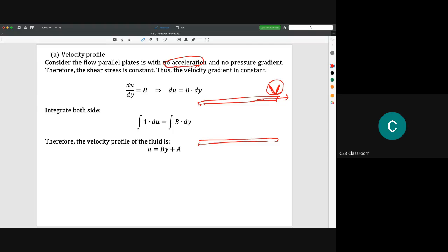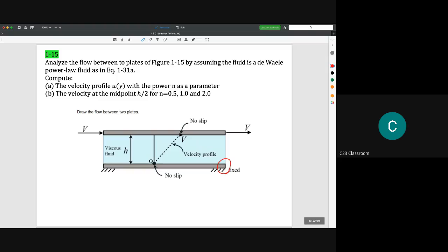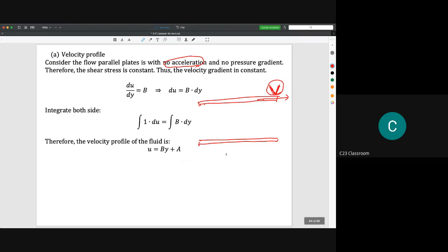Normally in this situation, with a fixed and moving plate, we will use liquid inside the plates, because it is not easy to control if you put any gas here. The gas will vaporize and so on. From the Bernoulli equation, we could say that the level here is equal, so we could neglect the potential energy Z. You know the Bernoulli equation, P over rho g and so on.